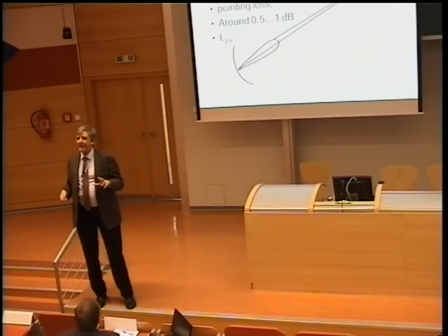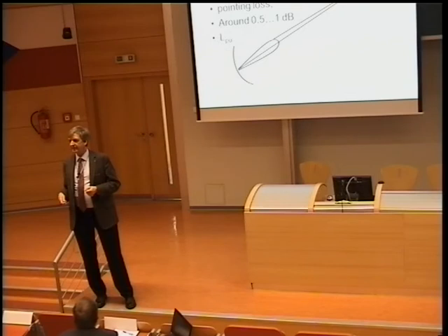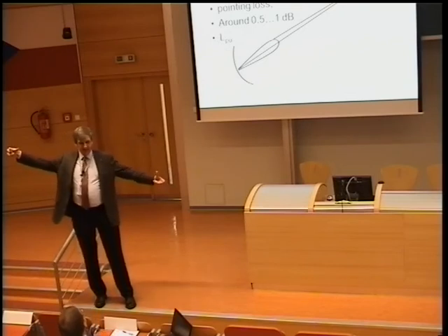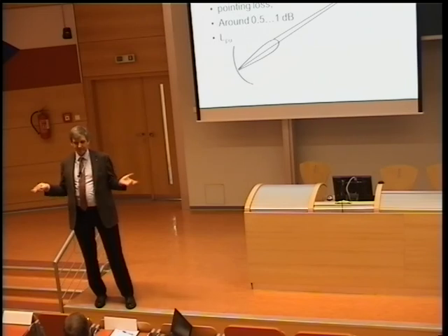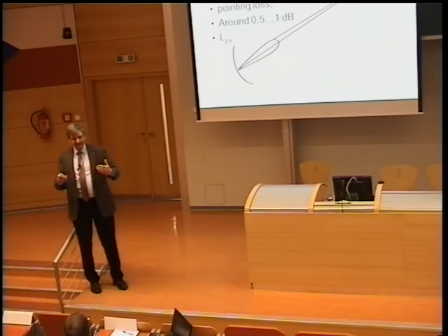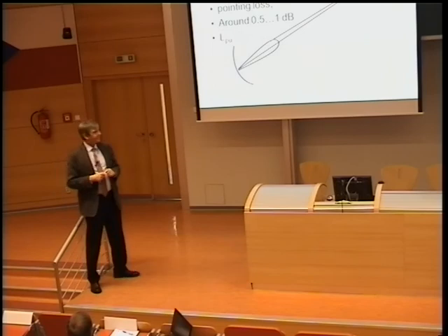However, I mean, with amateur radio ground stations, you typically have quite low-cost rotators, and the cheap ones have a pointing accuracy of about 3 degrees. If you have now a quite high-gain Yagi antenna, the half-power beamwidth, or if you have a dish, then the half-power beamwidth is in the same order of magnitude. And then if the tracking has not got the proper resolution, you will have some pointing loss there.